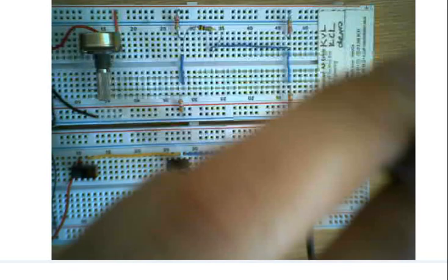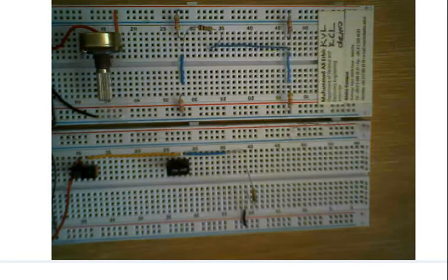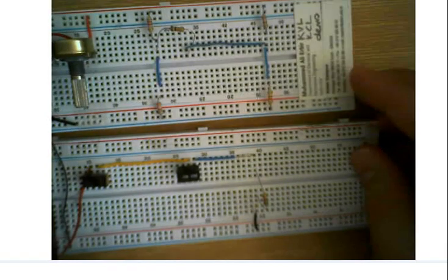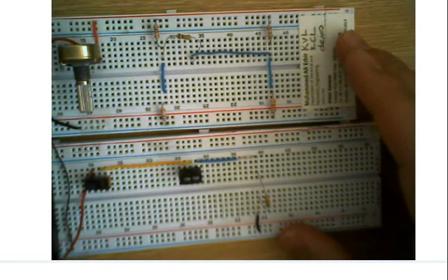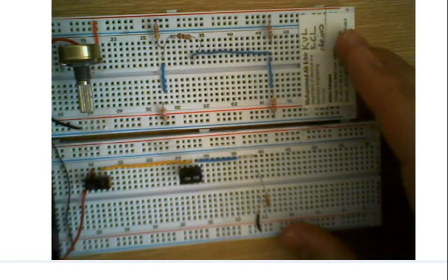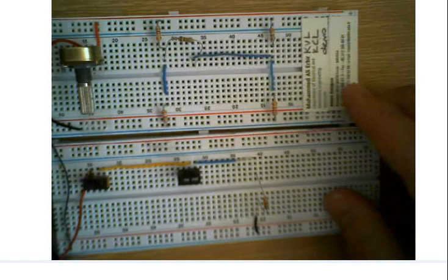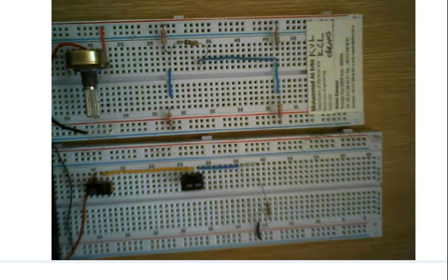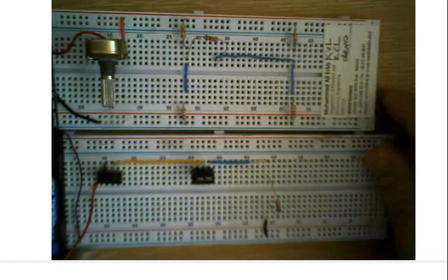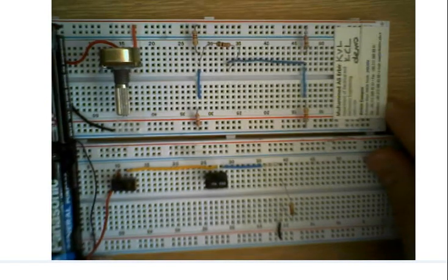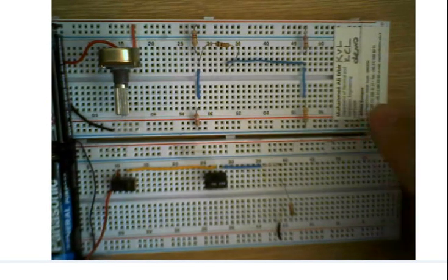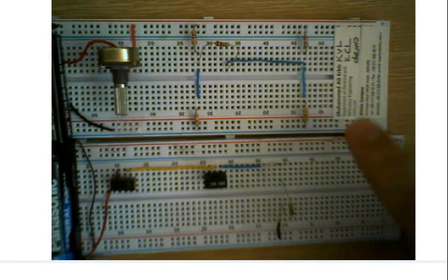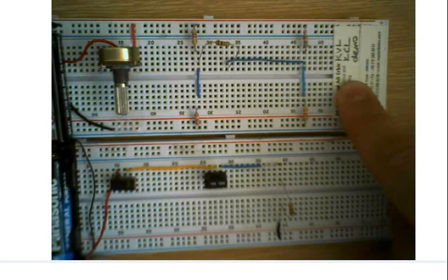So my Thevenin equivalent circuit works, okay? It holds for different situations. It has the same open circuit voltage, same resistance. It has the same response for 1 kilo ohm, same response for 10 kilo ohm resistors, okay? So they work identically. They have the same properties. So I can use this Thevenin equivalent circuit for this one, okay?